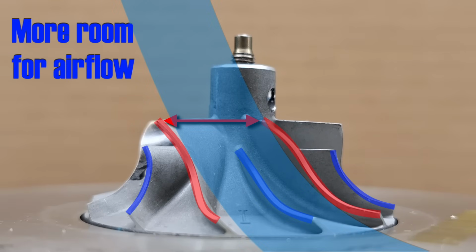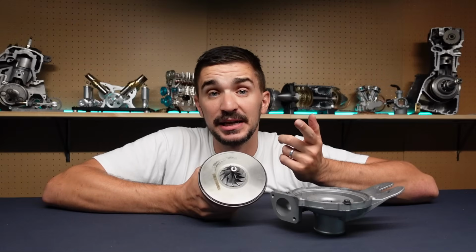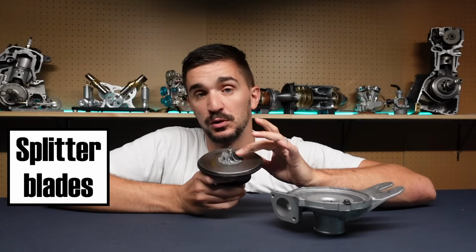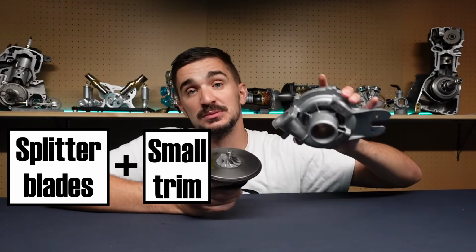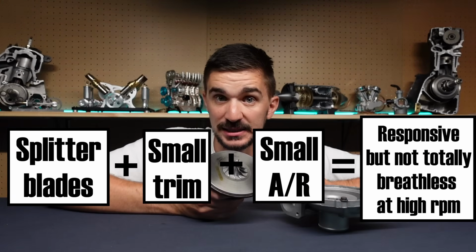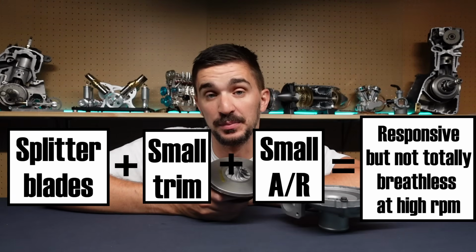So a compressor wheel like this one is well suited for high RPM performance and allows a higher peak boost pressure at the expense of a slightly increased boost threshold. Stock applications will often combine a splitter blade design like this one together with a small trim on the wheel and a small A over R on the housing to create a good compromise between responsiveness and high RPM performance.